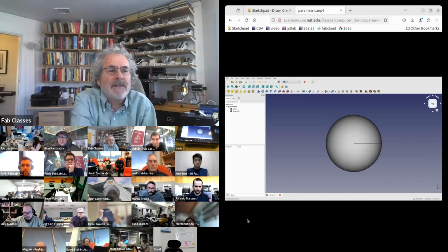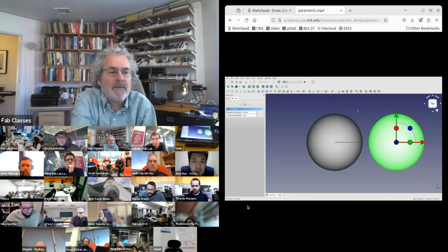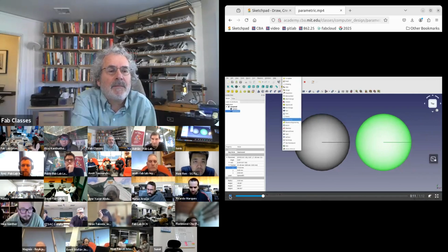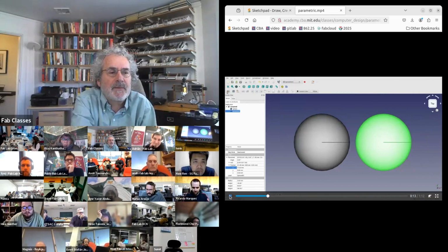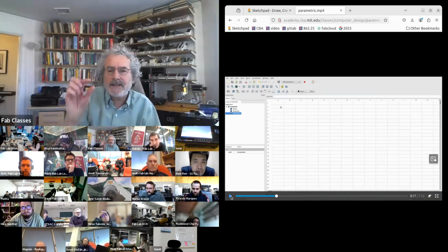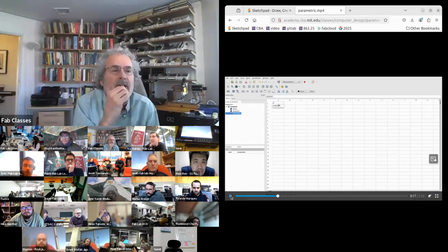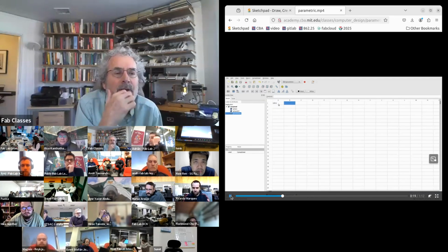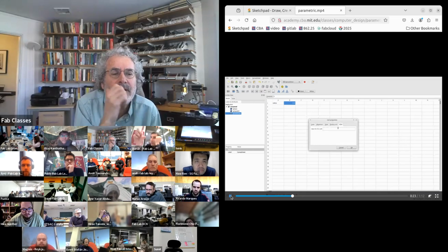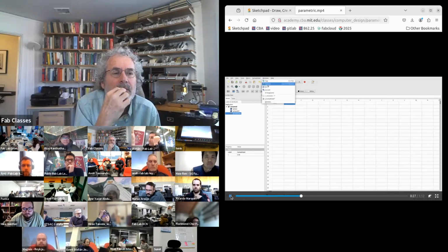So I'm going to make a design. And here are two parts of my design. Now I'm going to add a spreadsheet. The spreadsheet lets me enter variables and formulas. So I'm going to name a variable, radius. I'm going to give it a value, and I'm going to make it a math variable.